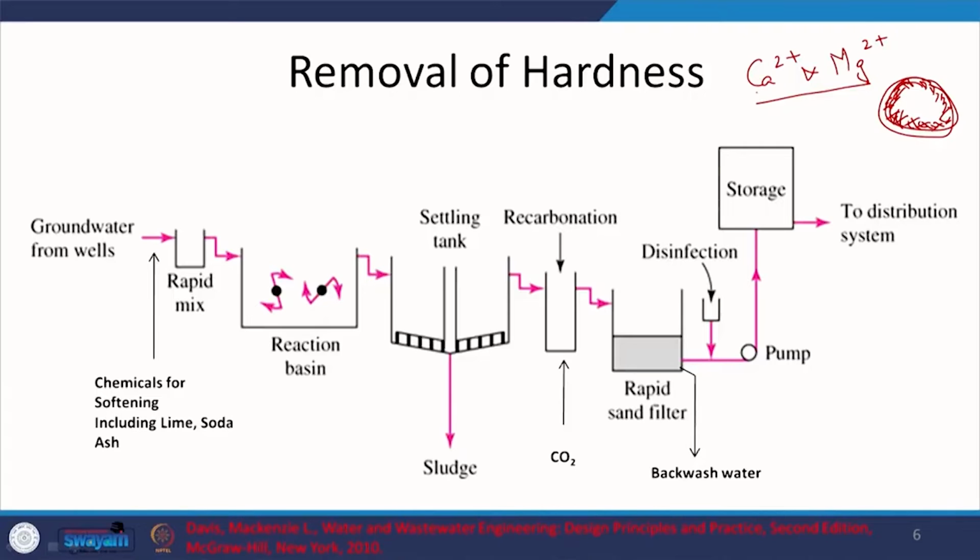One sure way of disinfection is boiling the water. To drink, we used to see that over time this vessel had scale being formed, and over time I had to supply energy at a greater intensity or heat the water for a longer time to be able to achieve the same level of final temperature. So obviously my heating efficiency is decreasing there. And why is this? It's because of precipitates, calcium and magnesium precipitation. Earlier they were dissolved in the solution. When I heated it, some forms will precipitate out, right.